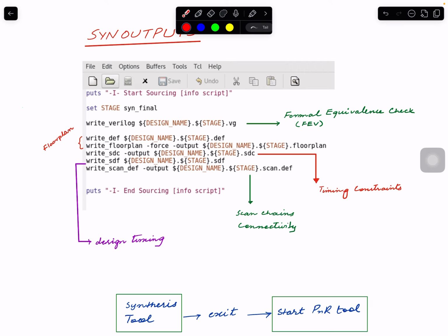Keep in mind that for the timing constraints you can create in any Tcl file, not every command is supported by SDC, which is the reason why it's useful to have a standard design format. So different tools can say, okay, we accept this standard design format.